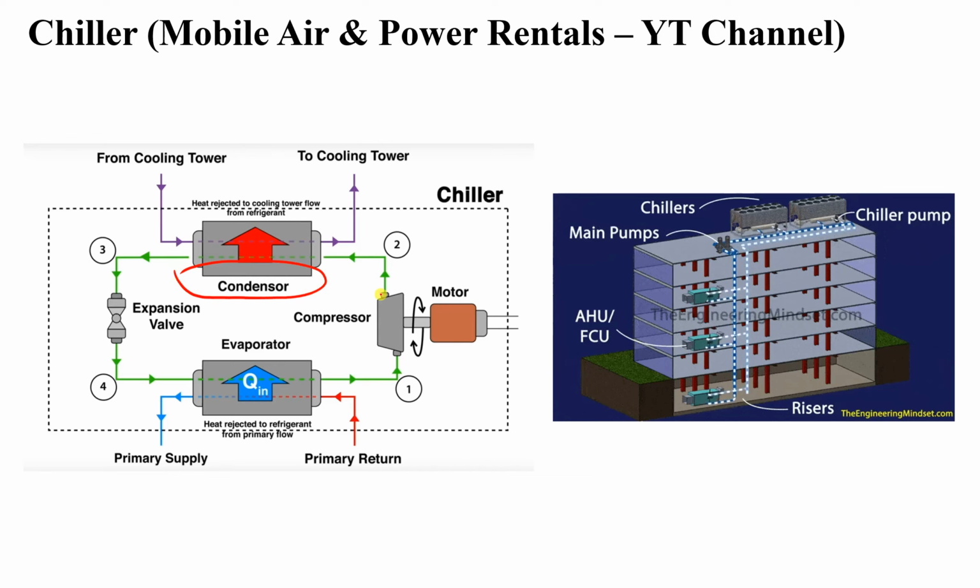So we have here a compressor that provides hot compressed Freon or refrigerant, right? Refrigerant. So what we are gonna do is that when we provide it to this condenser, we would like to cool it down to reduce its temperature. Now if you remember, in the outdoor unit in the DX system, we used a fan that will give heat energy to the outside. This type is called the air cooling method. However, there is another way that we can use water to cool it down.